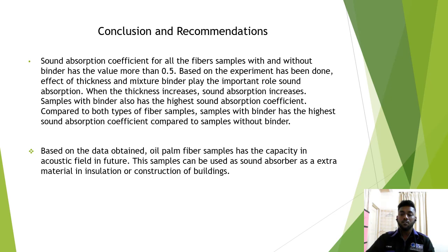For this final year project experiment, all the fiber samples, with or without binder, have sound absorption values of more than 0.5. Based on the result we obtained, the thickness and the mixture of binder play an important role in the sound absorption coefficient.